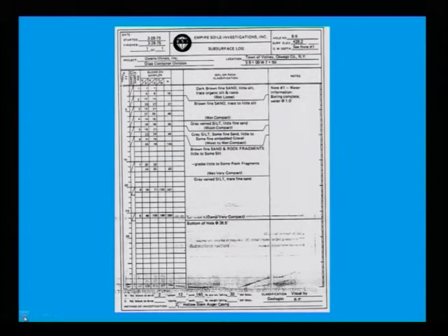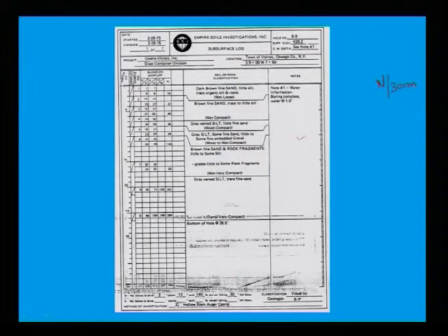One is the thing I have shown last class. This way also you can report, that means column 1 is your depth, second is your sample, third is your sample number 1, 2, 3, 4, 5. Then you can show blows on sampler, that means you can show the 3 blows, how the SPT has been done. Sometimes the design engineer also asks, instead of showing N per 30 centimeter blow, you can show the entire N count.